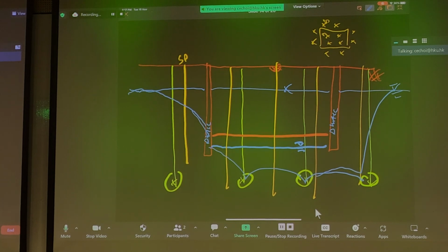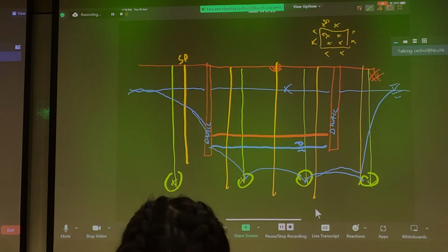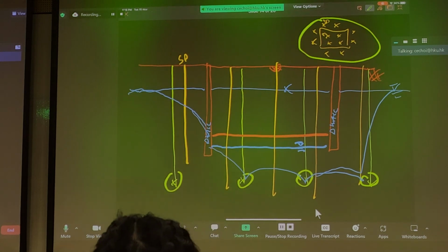Often, if you do calculations, seepage analysis, you might put in, let's say, 4 pumps, but you realize even 4 pumps is insufficient because we make a lot of assumptions in the permeability of the soil. During the ground investigation, we drill limited boreholes, so we may not understand the entire geology, right? And 4 pumps may not work. And then during your pumping test, let's say you cannot suppress the groundwater table, then you need to install more pumps.